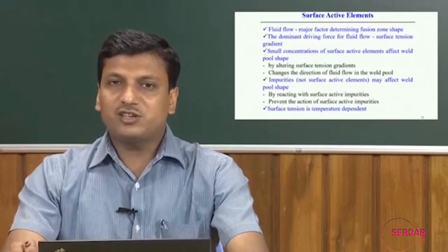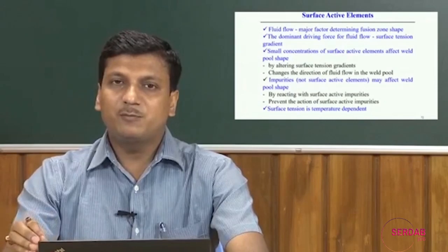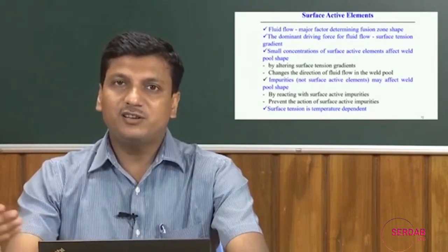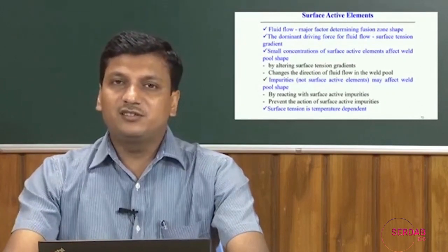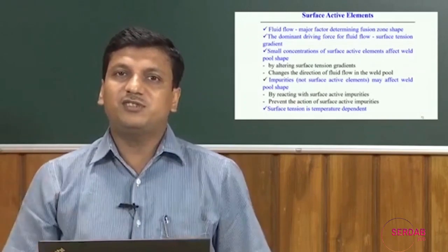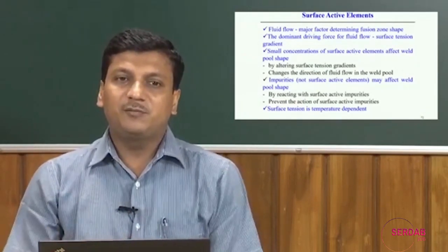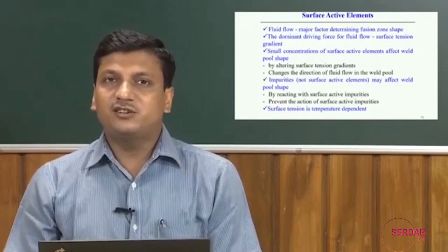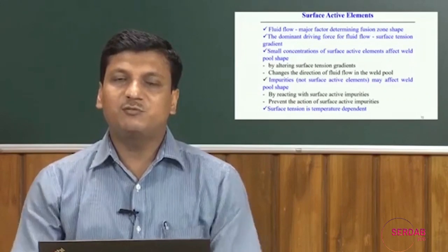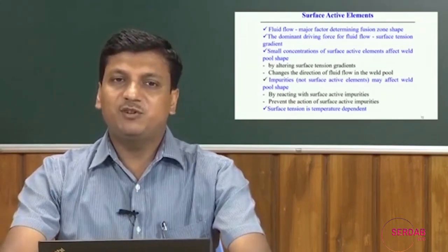A small concentration of these surface active elements affects the shape of the weld pool by altering the surface tension gradient. When there is a change of the surface tension gradient, there may be a change in the direction of the fluid flow in the weld pool, and that influences the shape of the weld pool.